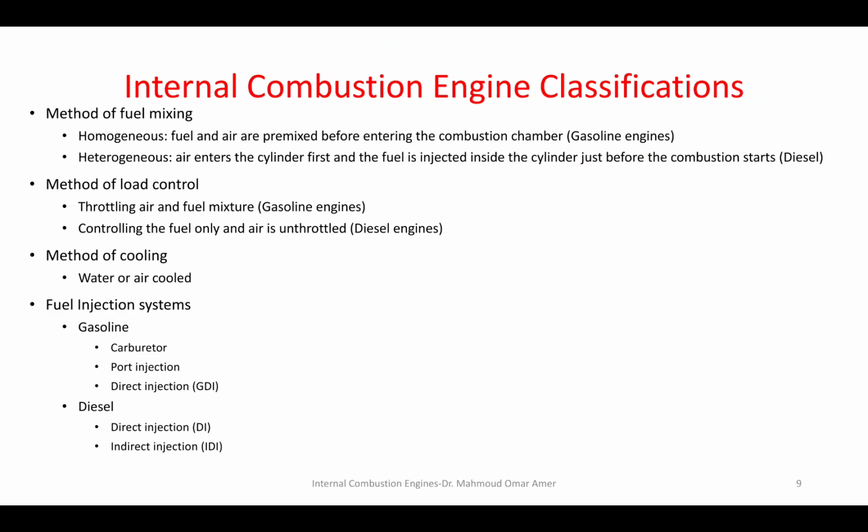Okay? But in diesel engines, when does the fuel mix with the air? Inside the cylinder. When exactly? Before combustion. Of course. We mix it before combustion starts. It mixes at the end of the compression stroke. So all the fluid inside the cylinder during the intake and the compression stroke is what? Air only. Okay? So does any mixing happen during the intake or the compression strokes? No. The mixing starts when the fuel is injected at the end of the compression stroke.